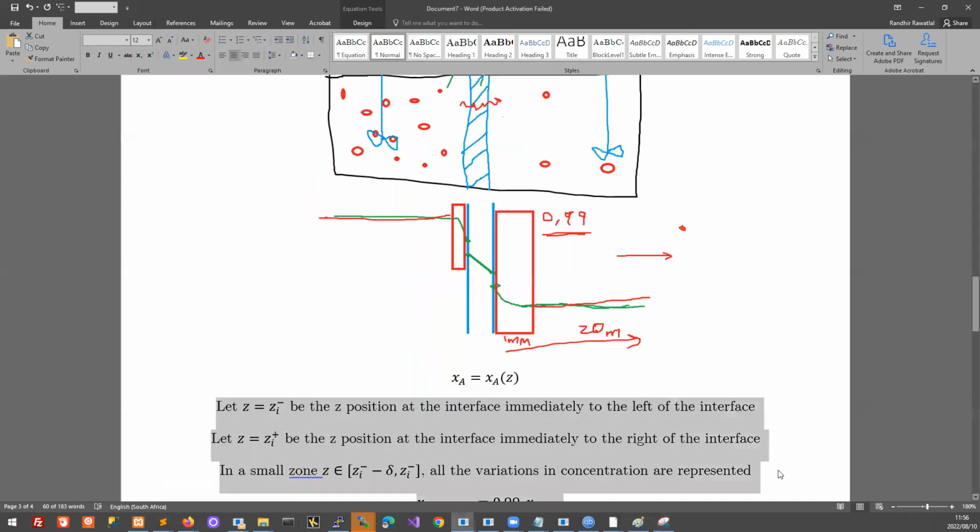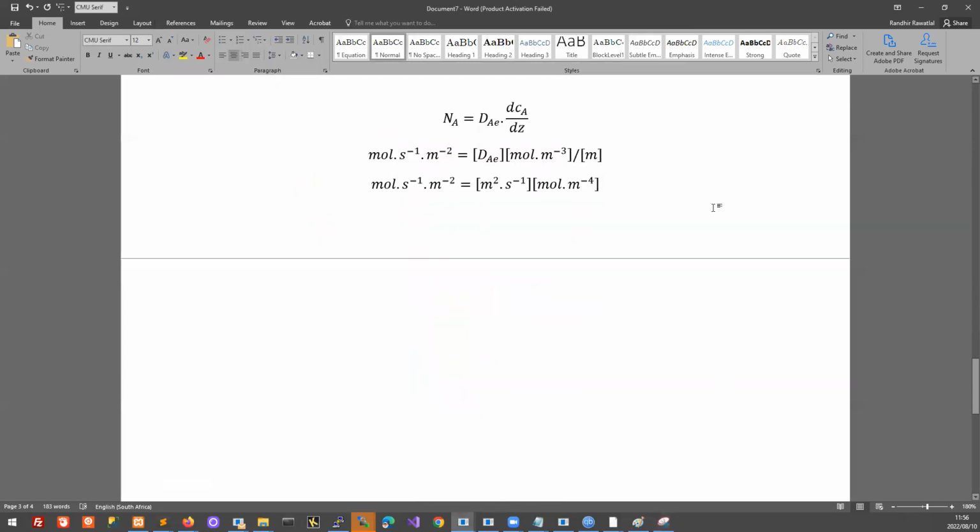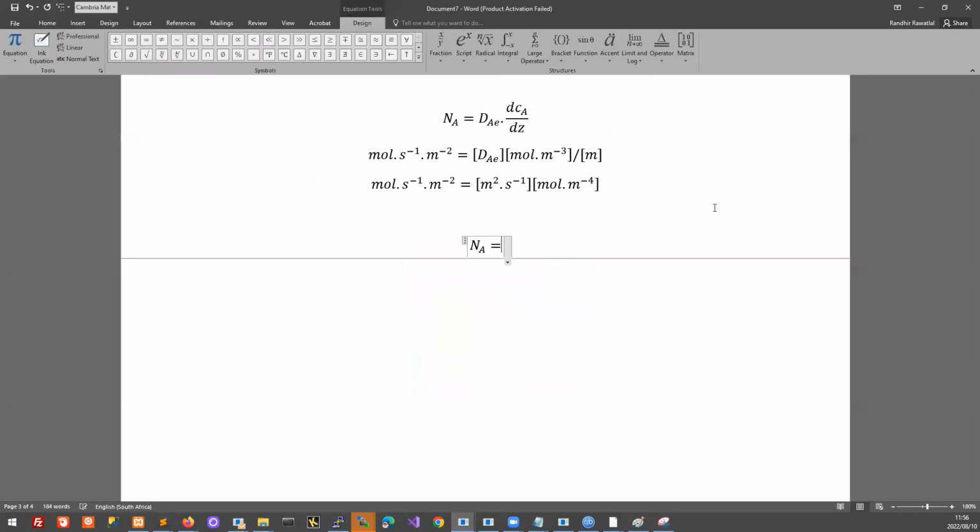So the way we do that is we say, well, your molar flux, N_A, really looks like this, right? Your molar flux, I want to write it like this. Okay, let's write it in the concentration form. So strictly speaking, we should be saying this, right? Let's just say z for now. However, I want to propose a much simpler form. I want to say, just make some constant, I'm going to call it k_c, times a concentration difference. And that's going to be the bulk value minus the interface value.